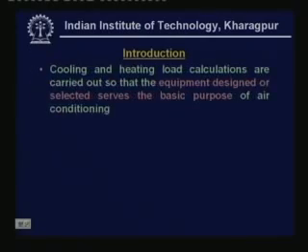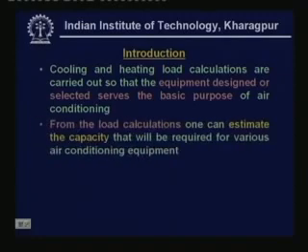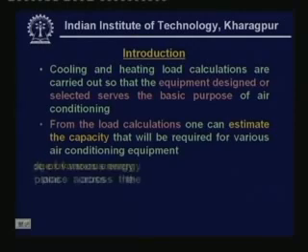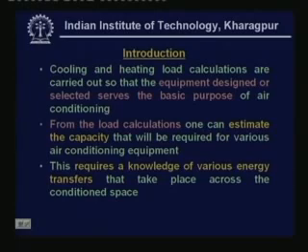Why do we have to carry out cooling and heating load calculations? Cooling and heating load calculations are carried out so that the equipment designed or selected serves the basic purpose of air conditioning. So this is a very important activity. From the load calculations one can estimate the capacity that will be required for various air conditioning equipment. And actually cooling and heating load calculation is a very stepwise procedure. It is a systematic stepwise procedure.